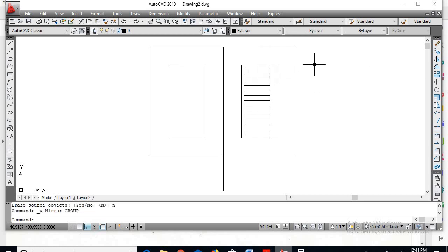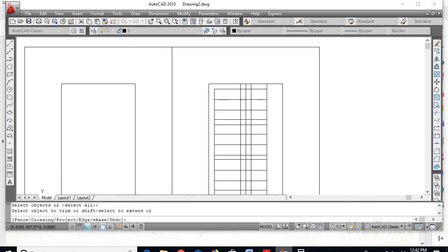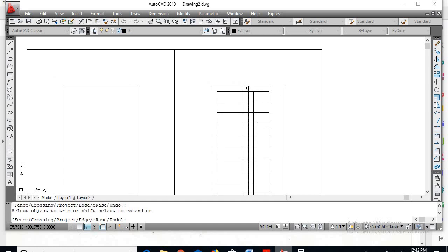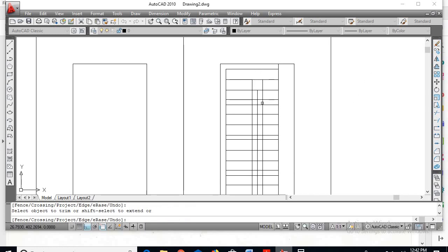So Control Z. So just I'll go for drawing a line from here. I'll take offset as 1 centimeter, enter. Towards right 1 centimeter, towards left 1 centimeter. So now I'll go for trim command, right click. So wherever there is an unwanted portion, remove those lines. So only the ducts can be shown at that particular point. So this is the duct.